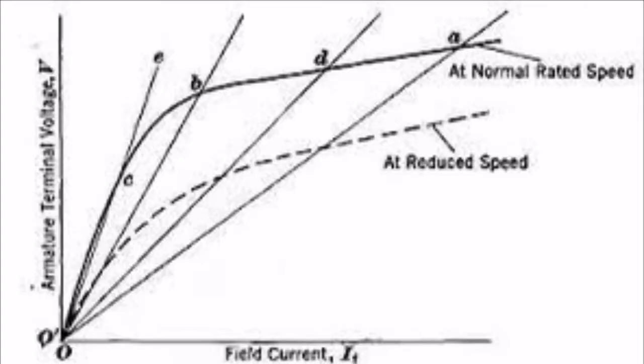Number 2. Failure to excite. Some reasons for failure to excite of a DC generator are the absence of residual magnetism, wrong field winding connection, wrong direction of rotation, resistance of field winding, or speed of rotation.